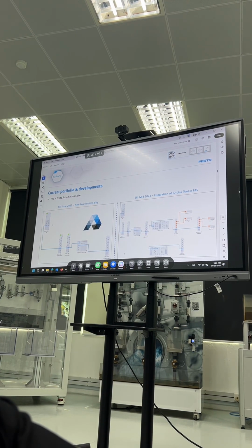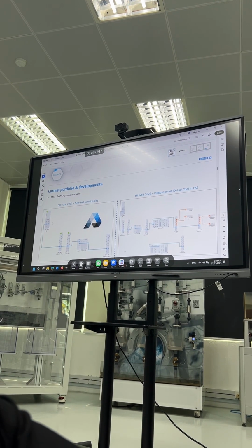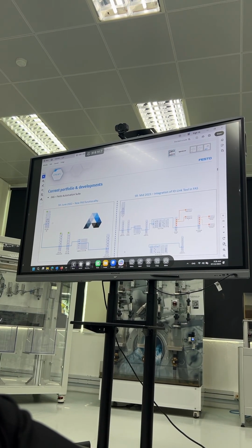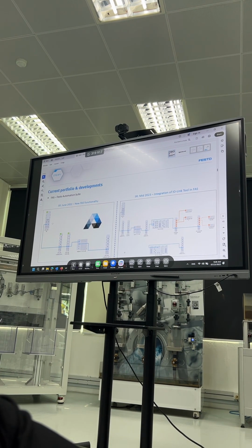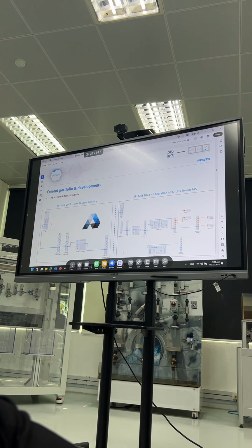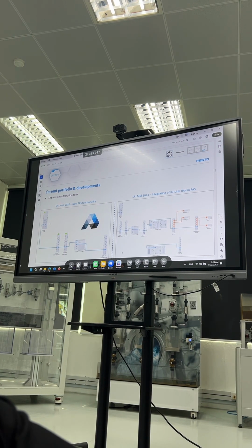When you enable this, the PLC will assign something like a virtual IP address to the EtherCAT slave. When the PLC has an EtherCAT connection to this slave and EoE is enabled, you will be able to access the web server this way as well.